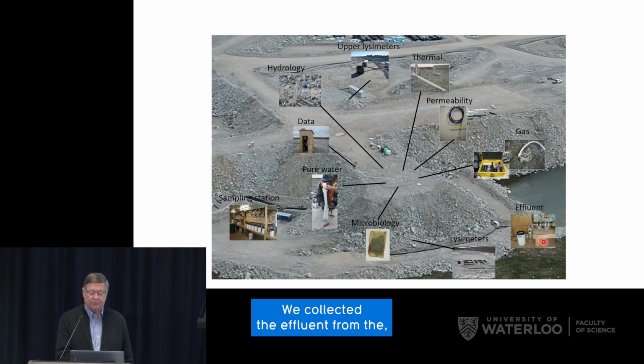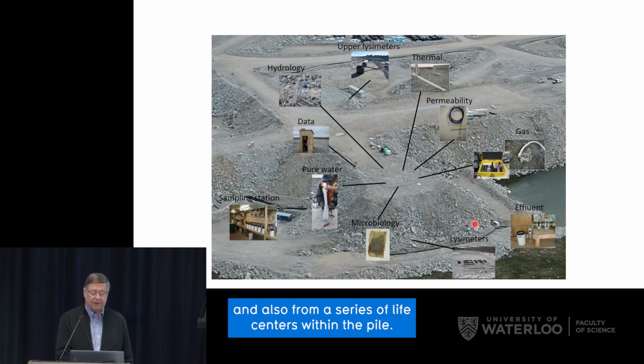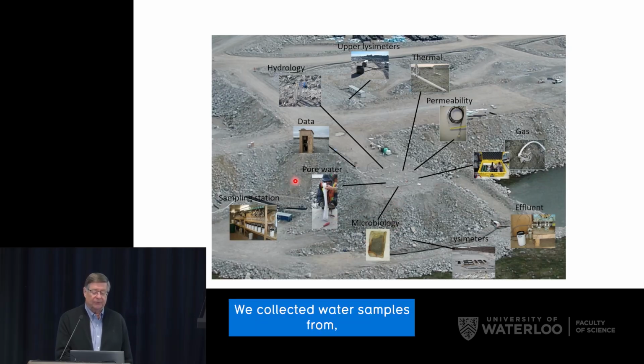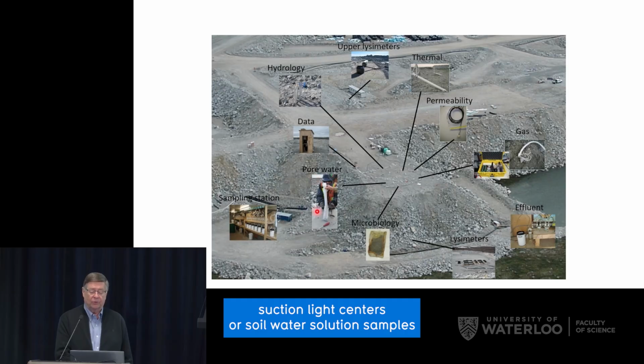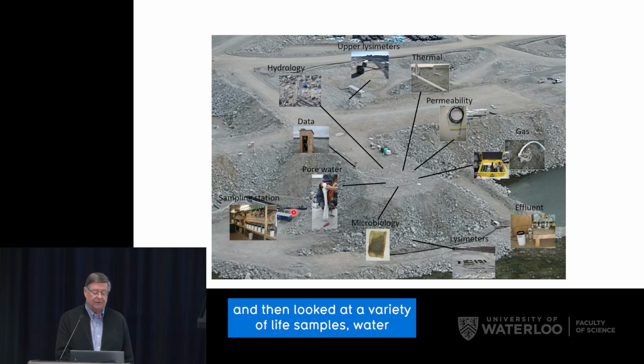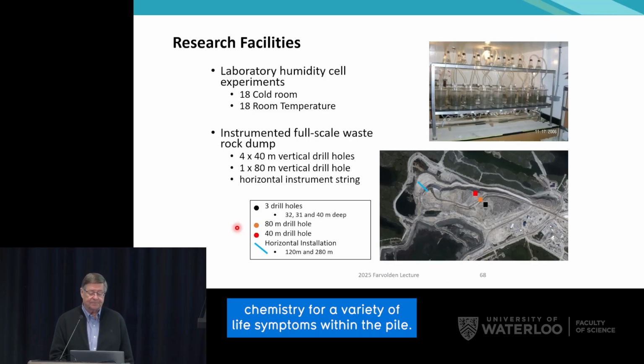We collected the effluent from the bottom of the pile and also from a series of lysimeters within the pile. We looked at the microbiology. We collected water samples from suction lysimeters, or soil water solution samplers, versus depth within the pile, and then looked at the water chemistry from a variety of lysimeters within the pile.